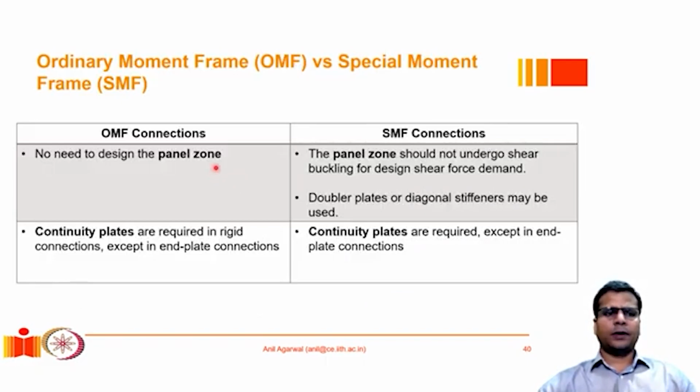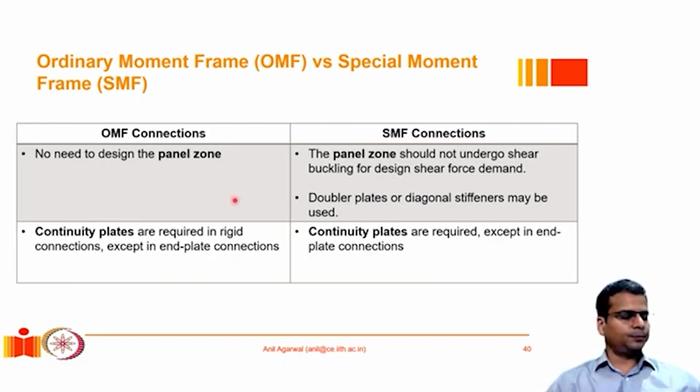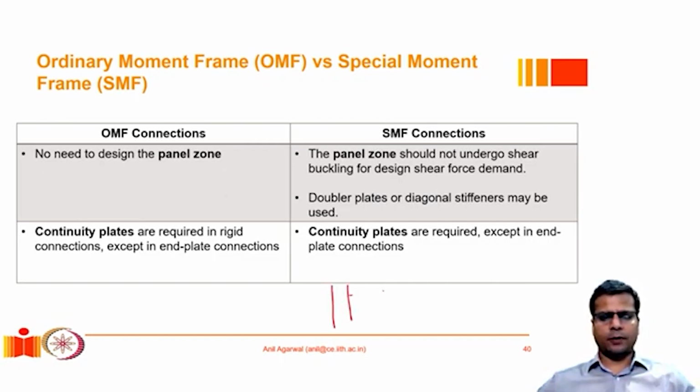Another aspect of a ductile design of a beam column joint is the development of a panel zone. So a panel zone is basically the intersection between the beam and the column. So let's say we have a column, and then we have two beams coming and meeting this column at this region, and then these beams want to rotate in this fashion, and let's say the column is held in its position. So this will basically produce some kind of a shear panel zone in this system.